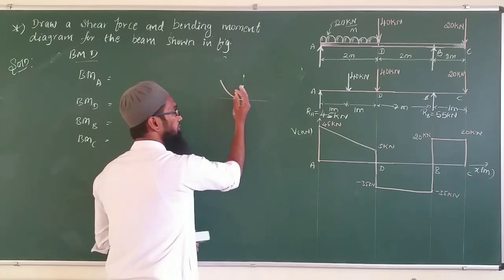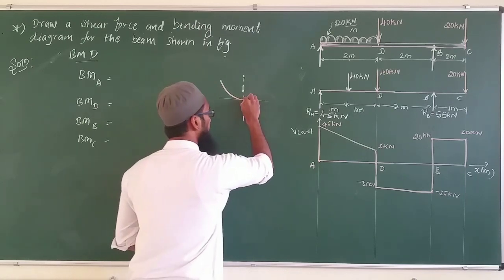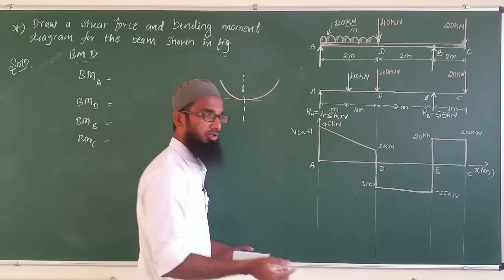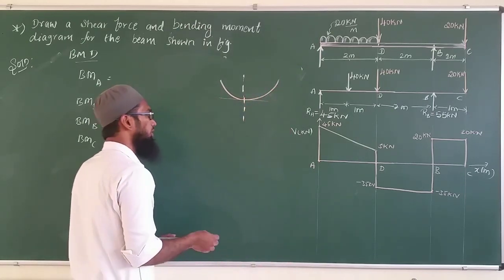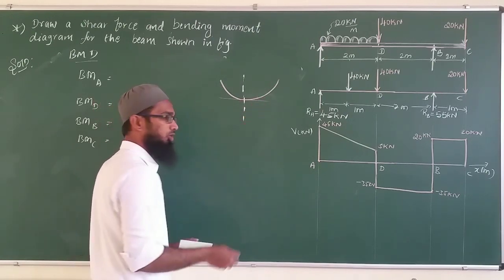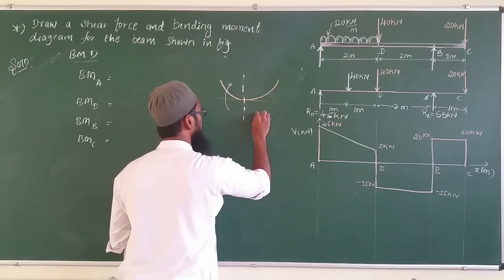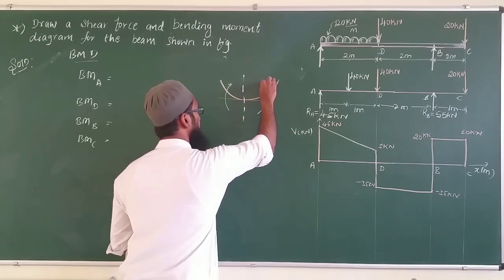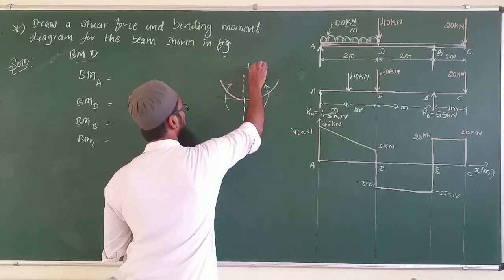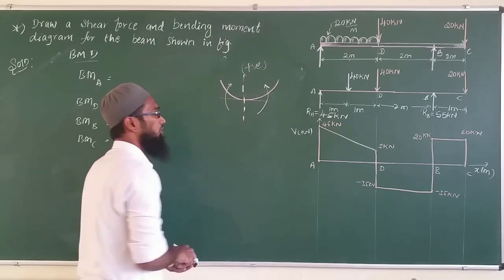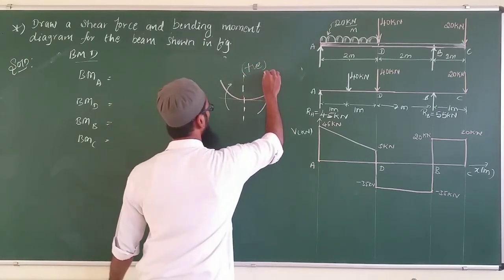by considering the moment here, if the beam bends like this on the left of this reference point, and again on the right-hand side the beam bends like this because of the applied load in any direction, depending. Okay, now this is the bending because of the applied load like this. Because of that we have calculated the moment, which gives the positive bending moment here. Now this is called a sagging moment.